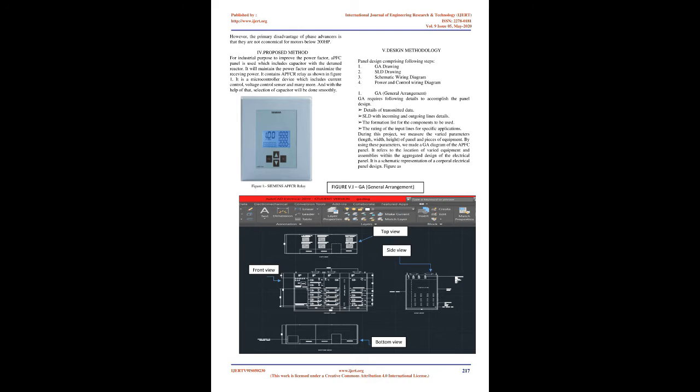Power factor correction is the process of compensating a lagging current by a leading current through connecting a capacitor to the supply. Practically, correcting the power factor much nearer to one may result in harmonic distortion. APFC, or automatic power factor control, panels are mostly used in the improvement of power factor.